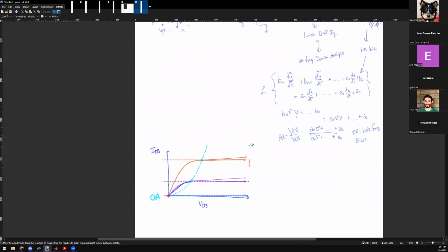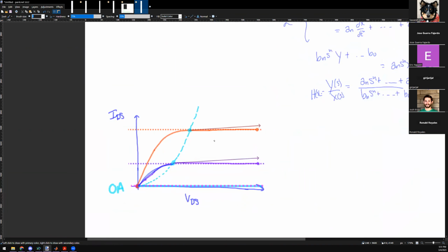So in this guy, for example, let's pretend I wanted to know. This clearly is not linear. First off, let's look at the red curve. Let's operate on the red curve. So let's say I want to operate here. So it's basically flat, then it's on, then it's flat, right? Awful, right? So it's non-linear, I mean, it's piecewise, just awful. So let's say, hey Eric, I know I operate in saturation, and I know that my VDS is going to have some perturbation. So here's VDS naught,